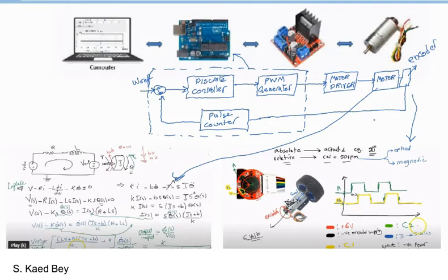As you may know, there is more than one approach to designing a controller for a plant, or the motor in our case. Because the motor, or our plant, together with the driver, are both in the continuous domain, we will leave the motor transfer function in the S domain and simply implement the controller in the Z domain, or the discrete form, in terms of difference equations.